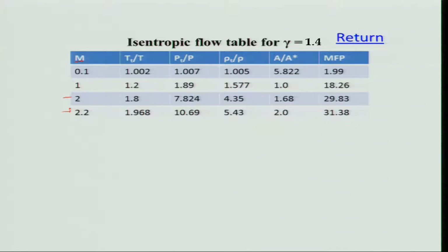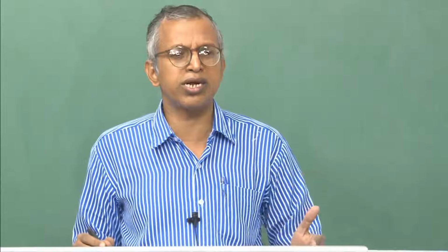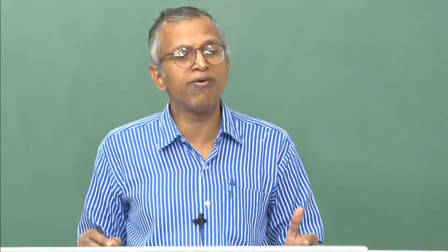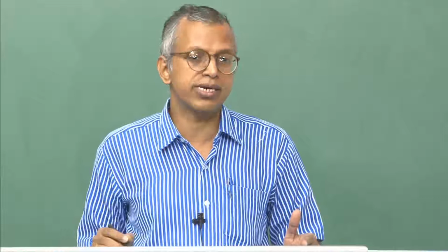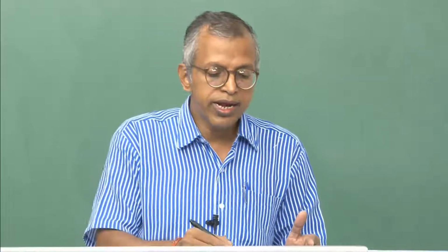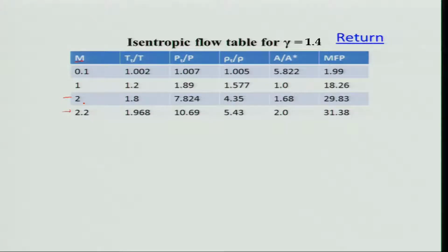You will have to do a linear interpolation between the data. That means you are assuming it to be linear. Are the relationships really linear? Certainly not, you have seen those expressions are nonlinear in nature, but we do it for simplicity, and it incurs certain errors, and those errors are very small and tolerable, provided the interval between two data points is small.